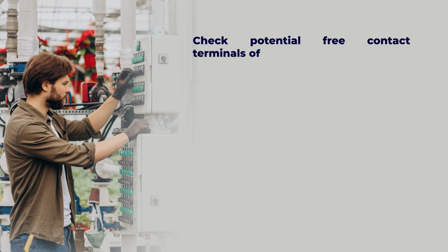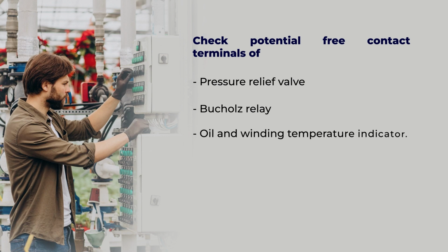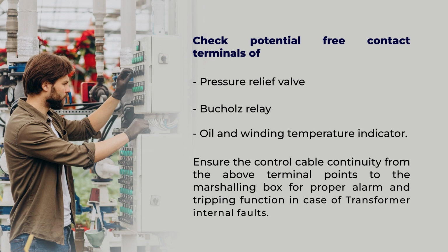Once this has been done, check potential free contact terminals of pressure relief valve, Buchholz relay, oil and winding temperature indicator.